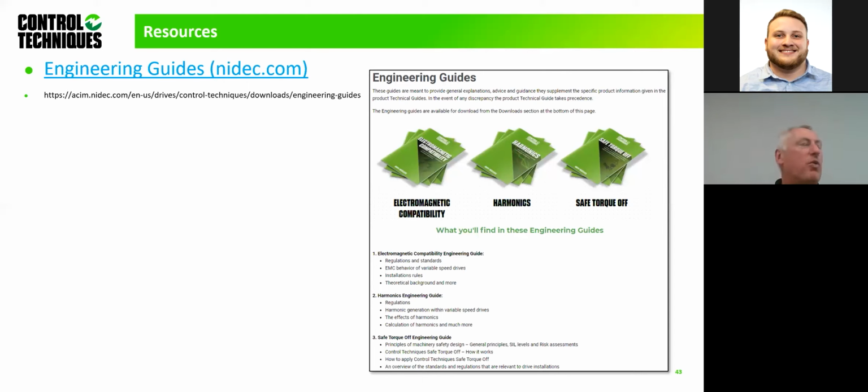But you're only worried about when it's starting up. And I can stand corrected here, because it's such a short time when it happens, it can impact equipment, and it could have a problem. Because it's a short time, it's hard to catch it affecting the equipment. So it depends on how often that soft starter comes on and off. I think it can be disruptive, just like a DC drive. The current harmonics on a DC drive are lower, but the biggest challenge with a DC drive, because of the thyristor commutation, is the notching effect.